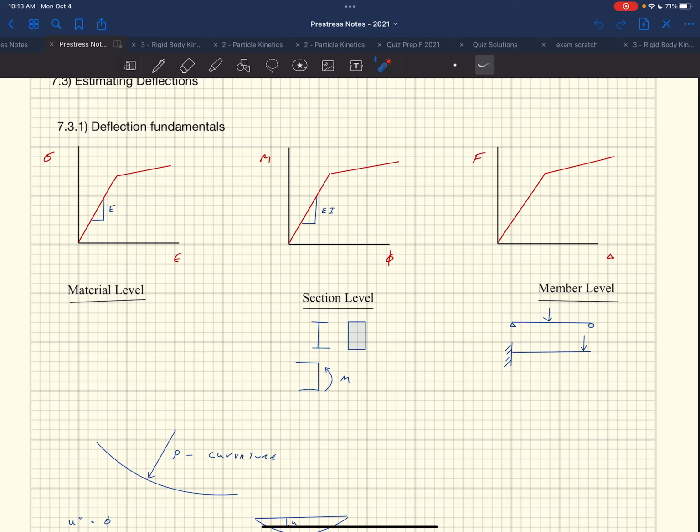The moment curvature relationship for this member is going to be different than for this one, which means when you go to the section level, the sections are calling on our stress strain response to see if the material is yielded or not yielded. That kind of governs where this comes from. All this stuff is at play as you're going along, especially when you go into nonlinear, okay? When we do elastic deformation, things get really easy because our stress strain response,